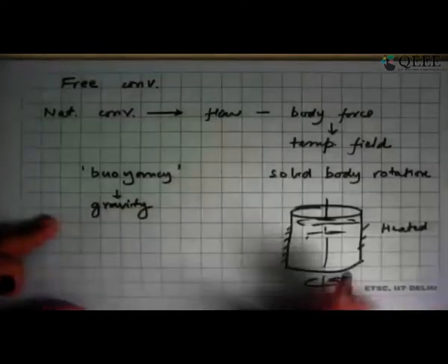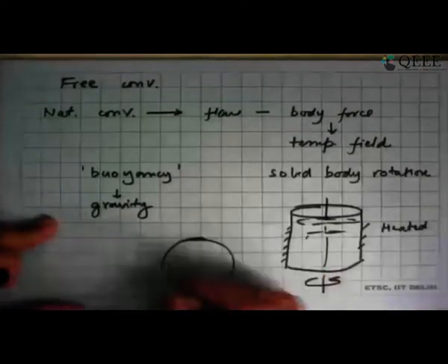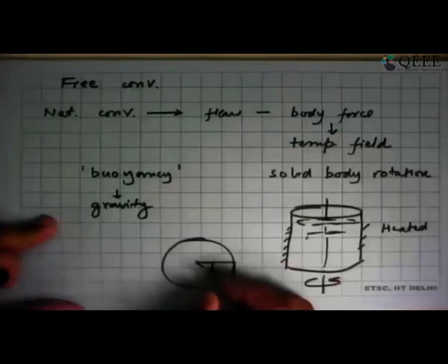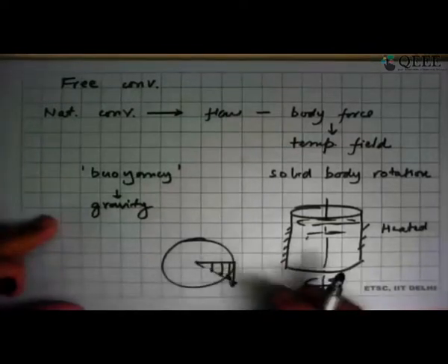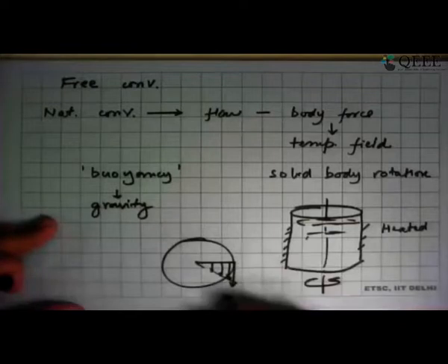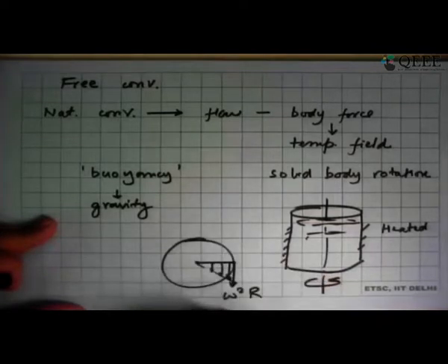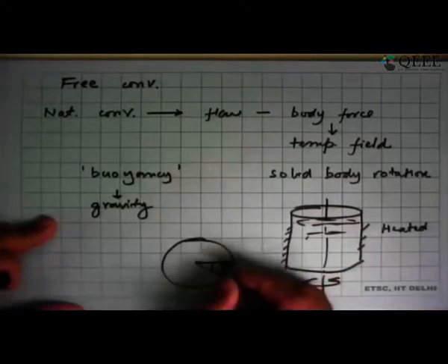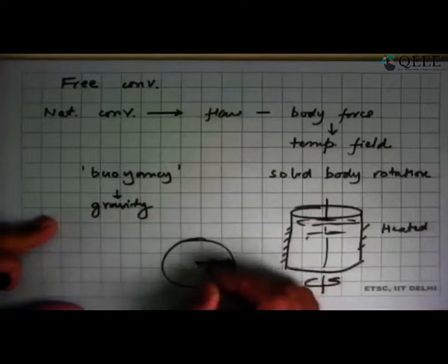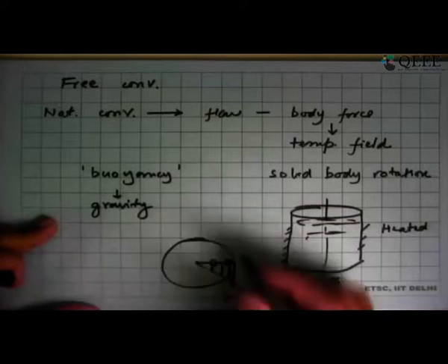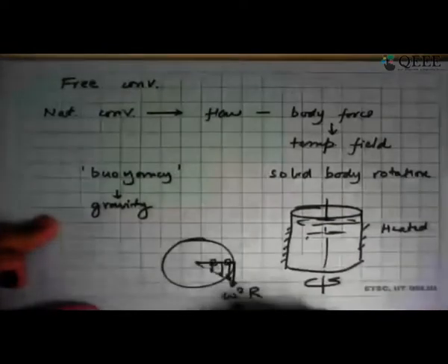Then what you have inside is a centrifugal force field, where the fluid is in solid body rotation and you have this velocity gradient. So you have omega square r there, and on top of that, when we enforce a temperature gradient, we will start generating elements here and here which have different density, different mass, and because of that they will experience different forces.